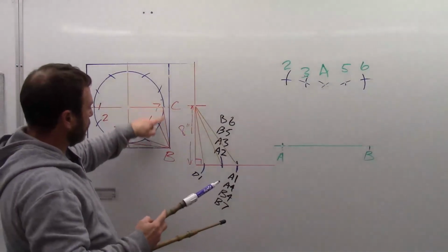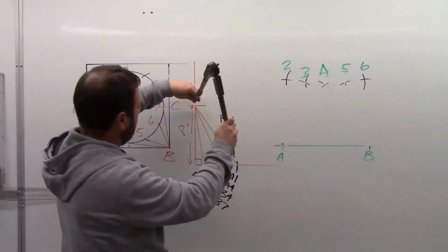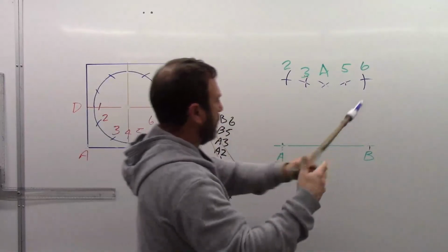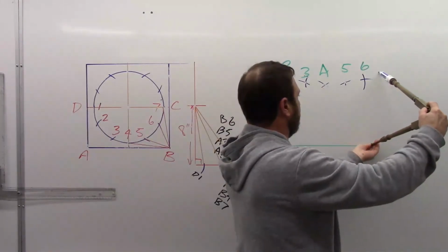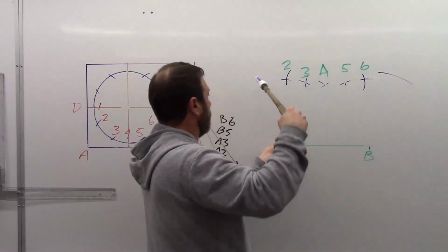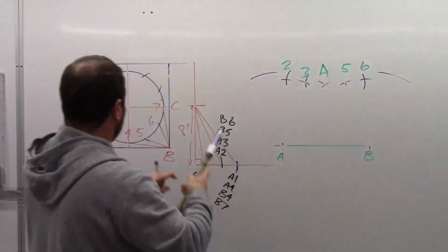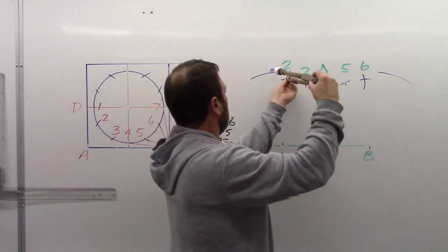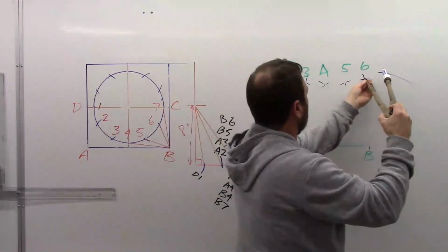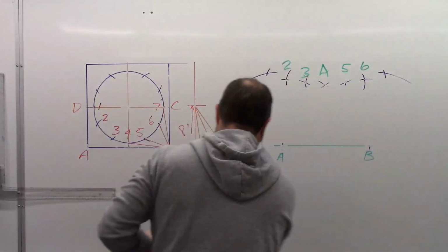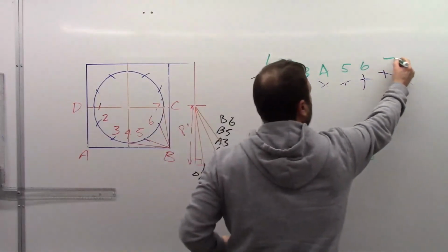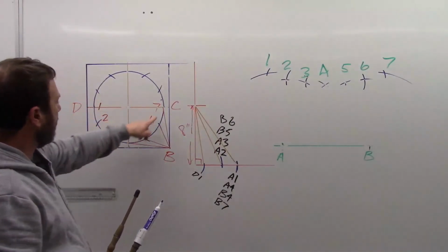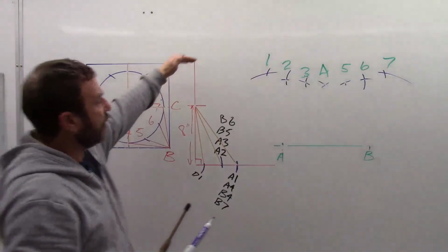So we'll take true length B7, which is again stretched out to our long one, and I swing it from B. And A1 from the other side, pick up my 1/12 division, and swing it to complete points 1 and 7. So now we've gone all the way at the top. We've gone all the way around the circumference here. So the top's complete.